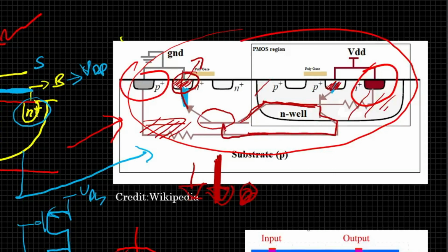So any time this thing gets forward biased, and you remove the disturbance so that this junction becomes reverse biased again, the current already supplied will keep this BJT on, and this will supply current again, which in turn makes the other junction forward biased, because a BJT turns on with current supplied to the base. So we have a loop here, a vicious cycle, and it will go on, and your MOSFET won't be working as you wanted. So you can roughly explain the latch up phenomenon like this.